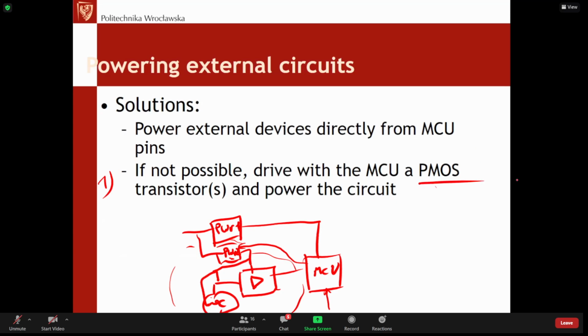I mentioned the PMOS transistor, because the PMOS is an element that can be used for this purpose. But today, fortunately, we've got linear regulators with an on-off pin, and this is especially for the sake of connecting a microcontroller, driving this linear regulator, and putting it down to sleep, for switching off the power supply for all the supplied circuitry.